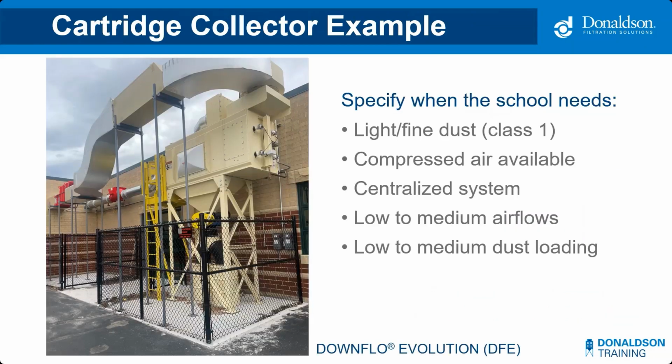The third item we're going to present here is the Downflow Evolution, the DFE cartridge collector again. It's the only one that can really handle either weld fume or wood dust. With the same system, you can mix the fume and the wood dust together. I tend to recommend this for schools when they combine the processes together.